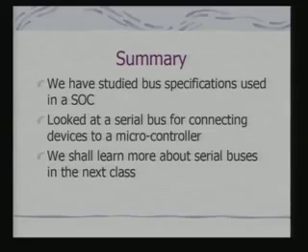So what we have done today is studied the bus specifications used typically in an SoC, and looked at the basic serial bus for connecting devices to a microcontroller. We shall learn more about the serial buses in the next class, because you have the SPI bus, and also the bus definitions for connecting peripheral devices. Other bus definitions, particularly for I/O devices like USB and FireWire, we shall look at in the next class.